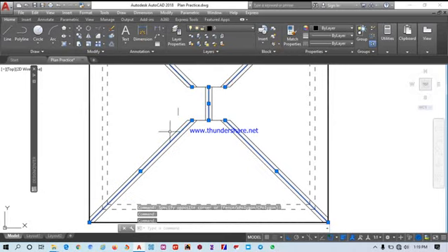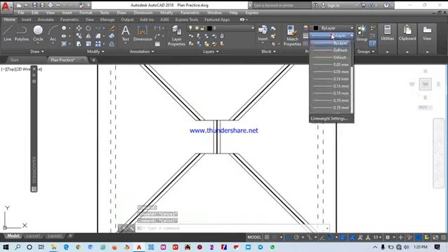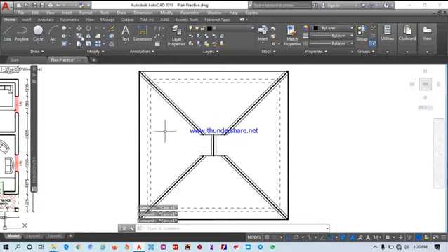So this center line on the ridge cap, there is a projection pointed. The ridge cap will be pointed at this area. So to relate that on your drawing, let me change it to a bold line of 0.3 thickness. By highlighting the line, I'm going to use line weight here. Go to 0.3. The next thing to do on our roof is to draw a kind of fork that shows the direction of the flow of water on each side of the roof.